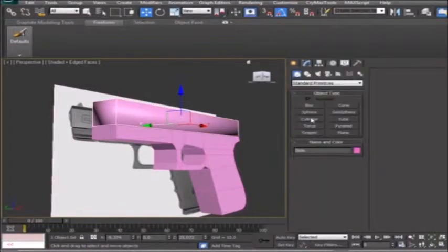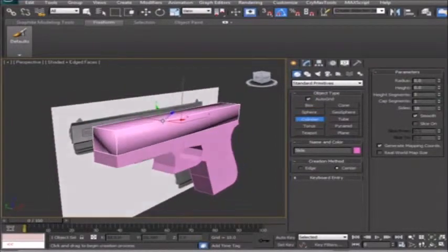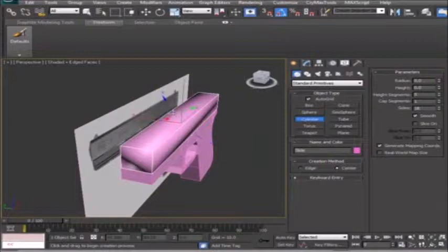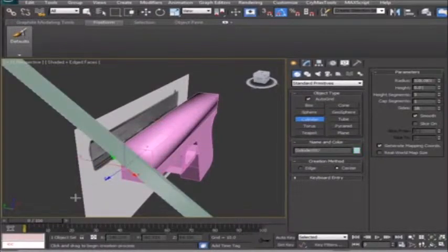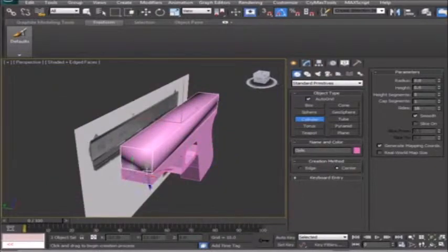Now you'll see that if I go to make a cylinder, you can see how it's curving around because it's trying to follow that smoothing factor of the normal. So if I draw it here, I'm not actually drawing straight up like I would be. I'm drawing out from a corner. It's the same thing here. It's trying to round this by smoothing it, so I end up with something going that way or that way.